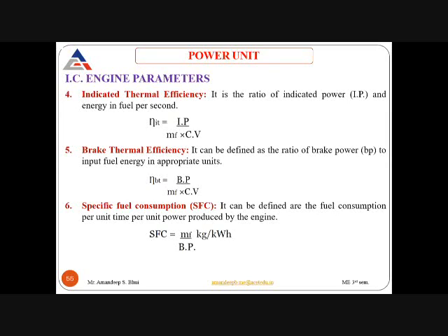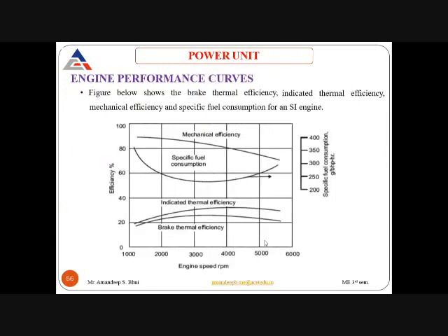It is given by the mass flow rate divided by the brake power of the engine. This will give me the specific fuel consumption of the engine. It is denoted in kilograms per kilowatt hour. So this is your specific fuel consumption.